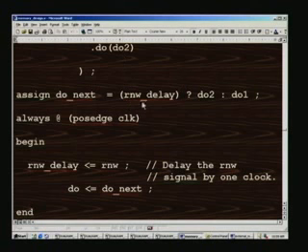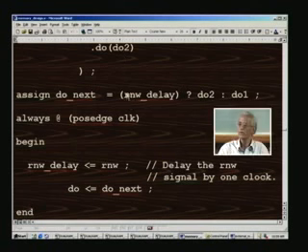And the reason for one delay being invoked here is to delay the actual R and W by 1 clock pulse, just to keep pace with this delay, because we are outputting after the clock edge. So in order to keep step with that, we are delaying that, otherwise the whole thing goes topsy-turvy. Just one error you make, the whole thing will become a totally dead system. And in fact I landed up in such trouble, and only after a few days could I discover that.